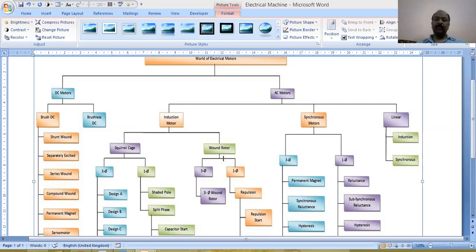at the ends of both parts of the winding. Whenever we talk about a winding, one part is the starting end and the other part is the ending end. If the starts are short circuited with each other and the ends are short circuited with each other, then it forms a cage. All the windings are joined over here and form a cylinder having a cage structure. So it is called the squirrel cage in nature, and it may be of two types, three phase or single phase.